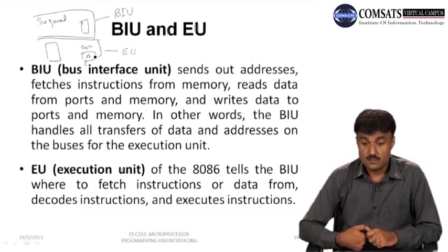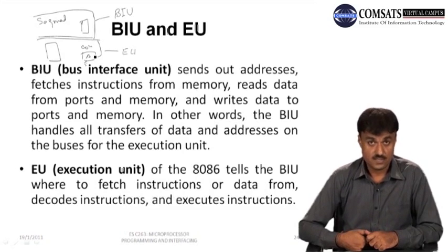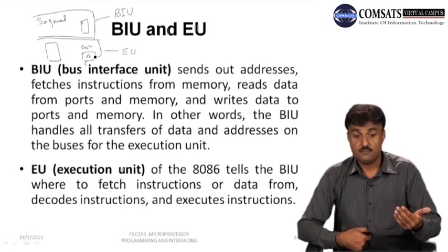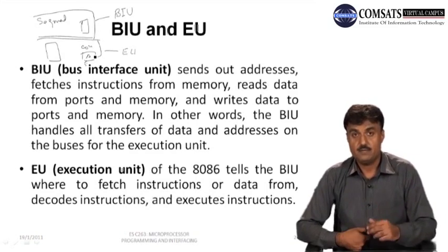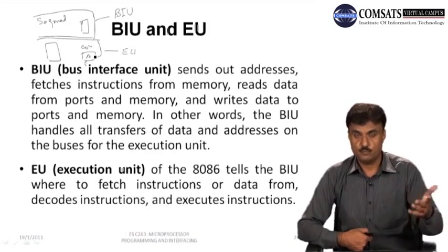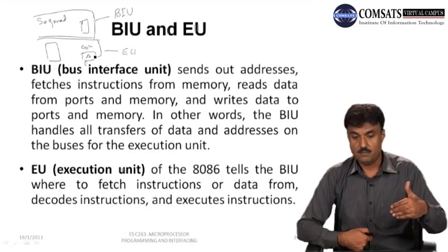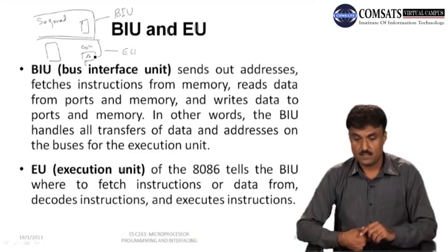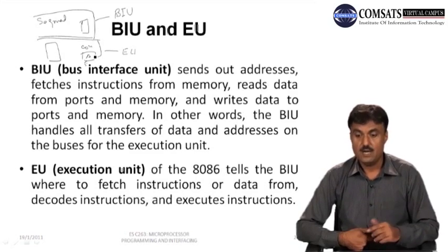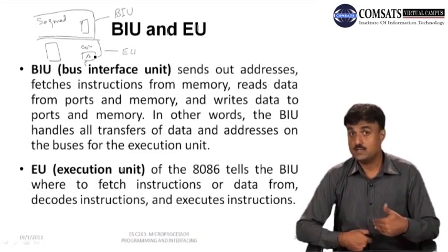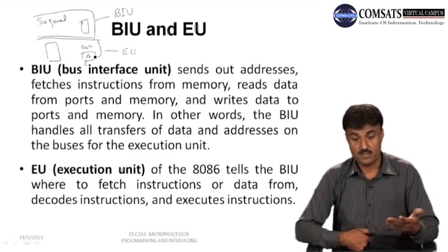What is the bus interface unit? It sends out addresses, fetches instructions, meaning it reads instructions from memory, and reads data from ports and memory. Ports means input output ports, if we are reading data from an input, or writing data to ports if we want to send data to the output devices or to the memory.